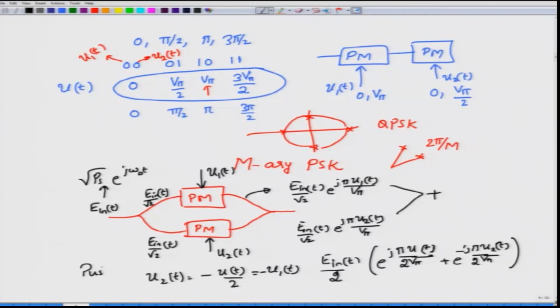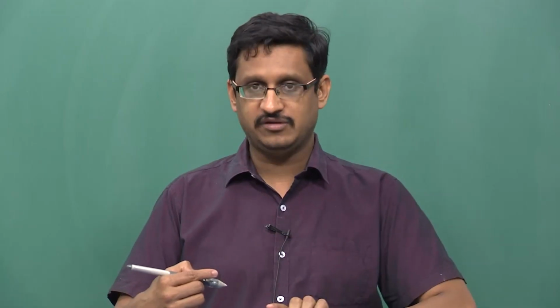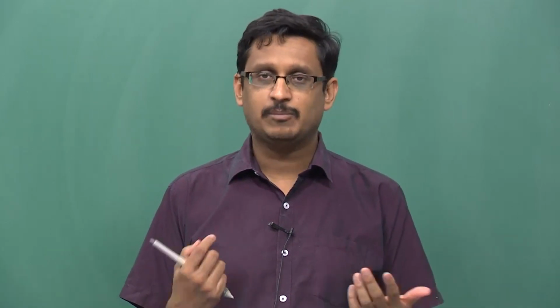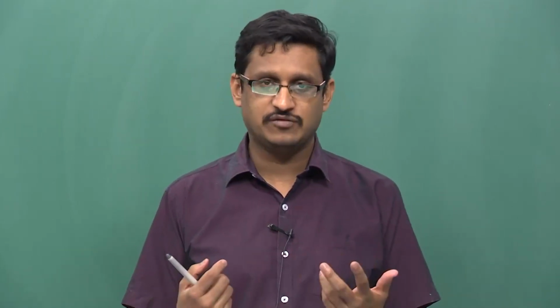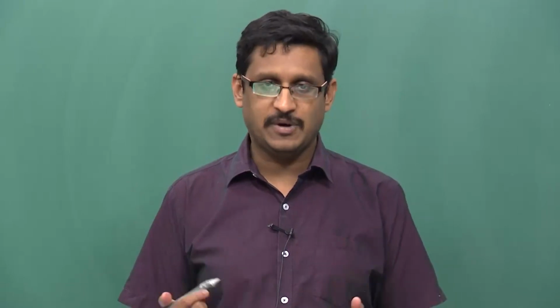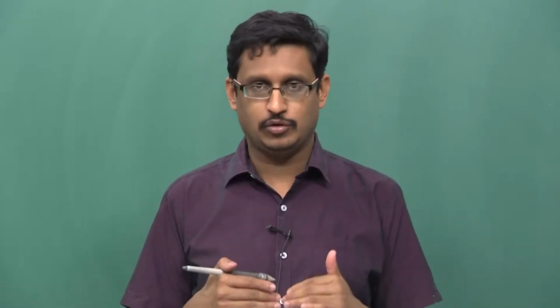This is called the push pull mode, and you can actually do that by going back to the electrodes that are present here, and then you tie these electrodes up to a constant or to the same signal, and then you apply an external u of t, which will be pushing them in this fashion. So, one phase modulator experiences an increased u, while the second phase modulator experiences a decreased u at the same time. This is just like making a plus VCC and minus VCC connection from a given power supply. That is exactly the same thing that we are going to do here.